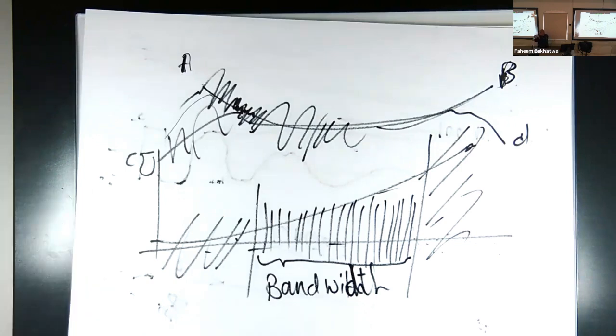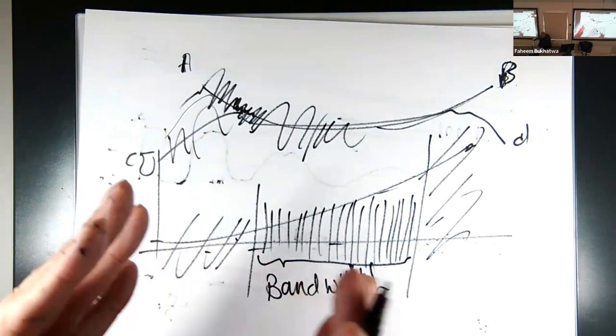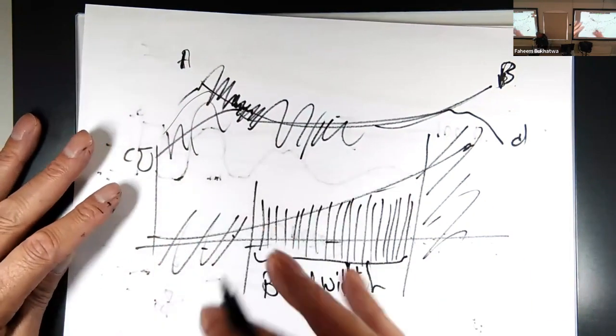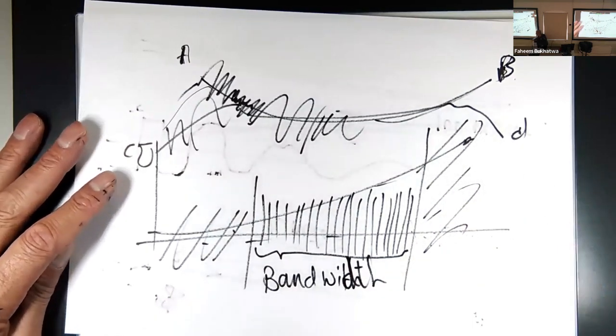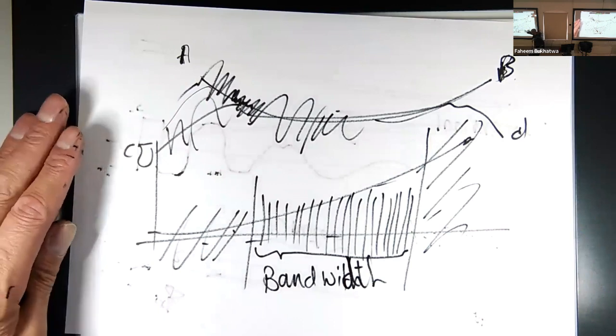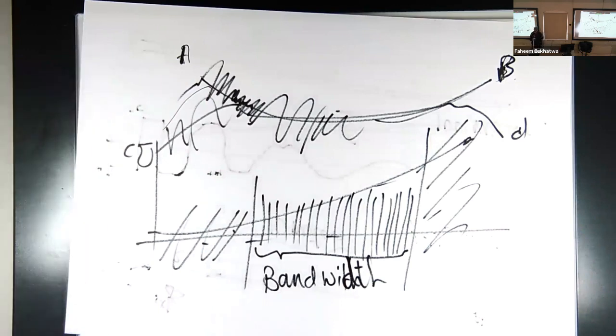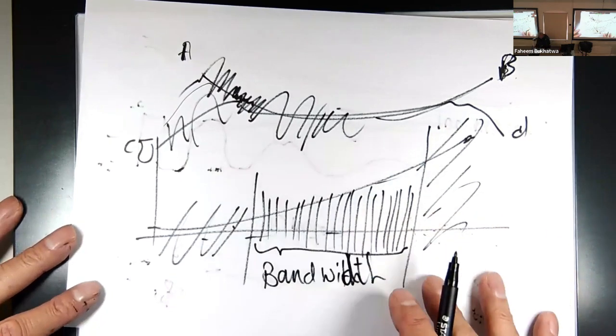So if you allocate 2 frequencies to some users, you can't allocate exactly the next number in frequency to the next user. There has to be a gap between them so there will be no interference. We don't need to deal with that, but that puts a limit on how many frequencies you can transmit on the same cable simultaneously. So that's either that as a definition.